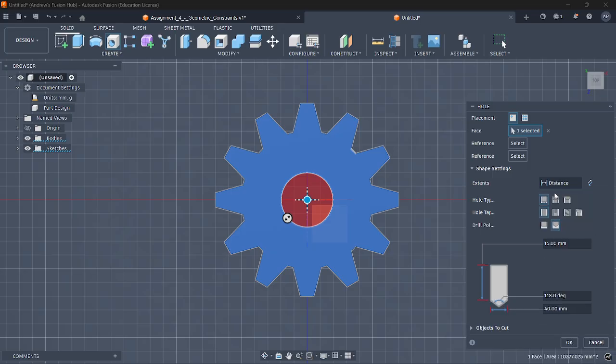But this is another little nitpicky thing. If you did an extruded sketch to some desired depth, it's usually going to be a straight hole, right? The bottom's not going to have a taper, but almost all drill bits that you would use will have some kind of taper on it, right? So that taper is modeled into your hole when you add it into Fusion.